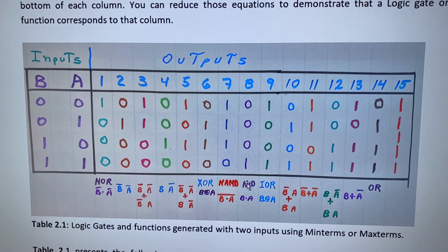So the opposite of the AND gate is the NOT AND gate, which we abbreviate as the NAND gate. And the NAND gate is the opposite of this column. And when I say the opposite, the logic is inverted. So you have ones at the output for these combinations, but when both inputs are 1, the NAND gate is 0.